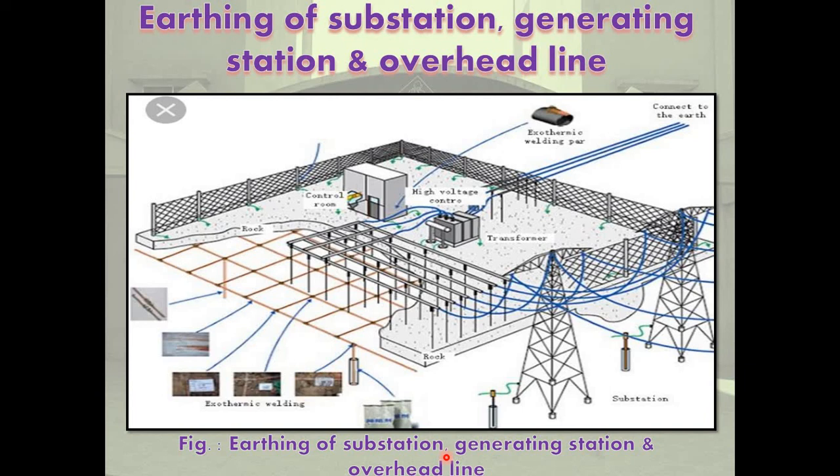Circuit breaker opening presents a change from current carrying state to voltage withstand state and produces switching surges due to sudden transfer of energy from inductance to shunt capacitance. First is low inductive current switching, like motor switching, transformer on no load switching, etc. The vacuum circuit breaker VCB, used for 3.3 kV to 33 kV systems, and the air blast circuit breaker ABCB, used formerly for EHV AC circuits and now obsolete, have a tendency to chop current before natural current zero.